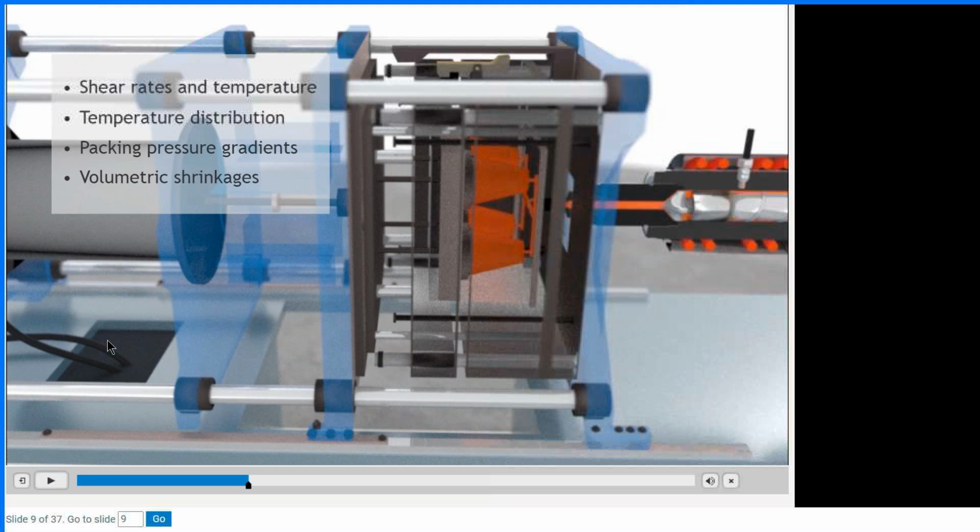These are just a few of the process conditions that will impact the temperature of the material inside the mold. Remember, a mold is a heat exchanger. The hot plastic is pushed into a cold mold, and a three-dimensional heat exchange will take place. In some areas, you may have an easier time withdrawing the heat from the plastic than in others. The wall thickness, of course, will play a role. So it is a huge can of worms that is very difficult to understand if you're not trained on cause and effect behavior from all of the components.